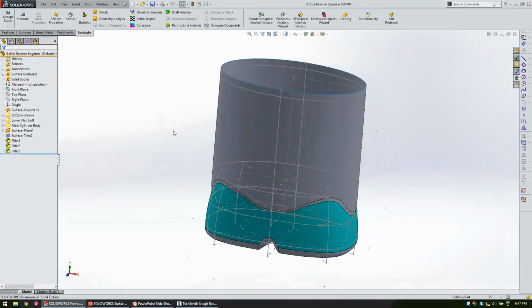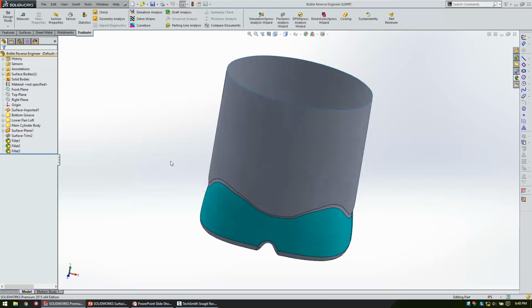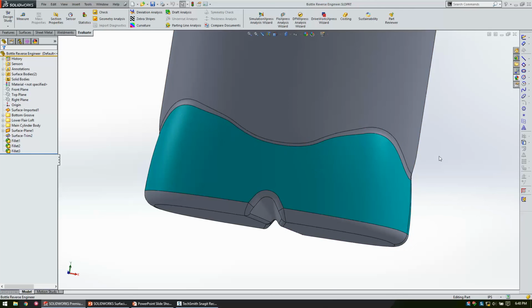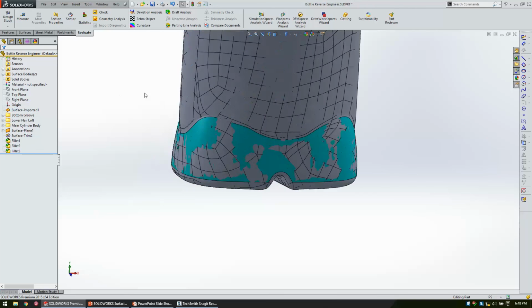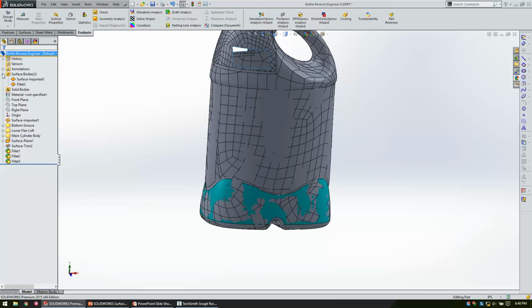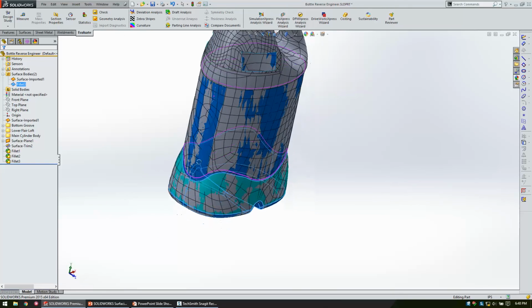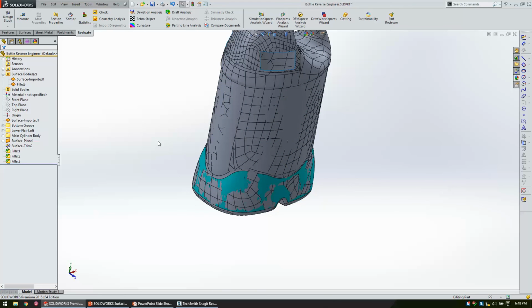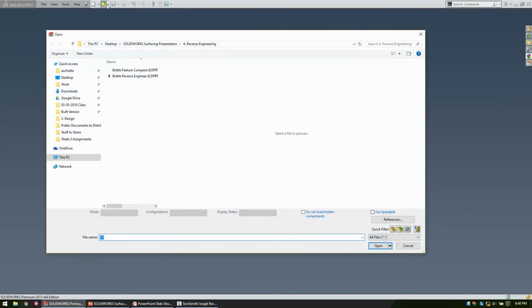So here's the same thing I just did, a little bit more. Turn off our sketches. You can see how I did the bottom floor relief and started filleting around to make this bottle look quite similar to what the scan was. It would look like that. Again, it all depends on your tolerance. I mean, this is plus or minus 10 or 15 thousandths, which for a plastic bottle is plenty good. They vary that much coming out of the blow molder.